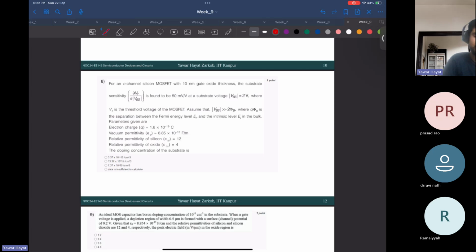Okay, what was your question then? My question is, shouldn't the graph rise up at different values of VG? Because as VD increases, the threshold value shouldn't remain the same, right? Your threshold is independent of VD, right? Threshold is a process parameter that has nothing to do with the bias.